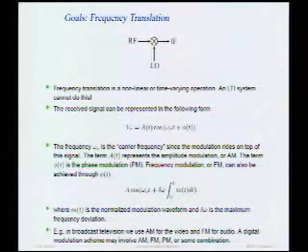And as I already mentioned, a linear time invariant system cannot perform frequency translation. So what is frequency translation? That means that you have an input at one frequency and an output that's at a different frequency. And one way to build a device that frequency translates is to use a nonlinearity. And we'll be looking at that in this course. Another way to do it is to use a time-varying circuit. And both approaches are actually valid ways of building mixers. Mixers are circuits that perform this frequency translation.